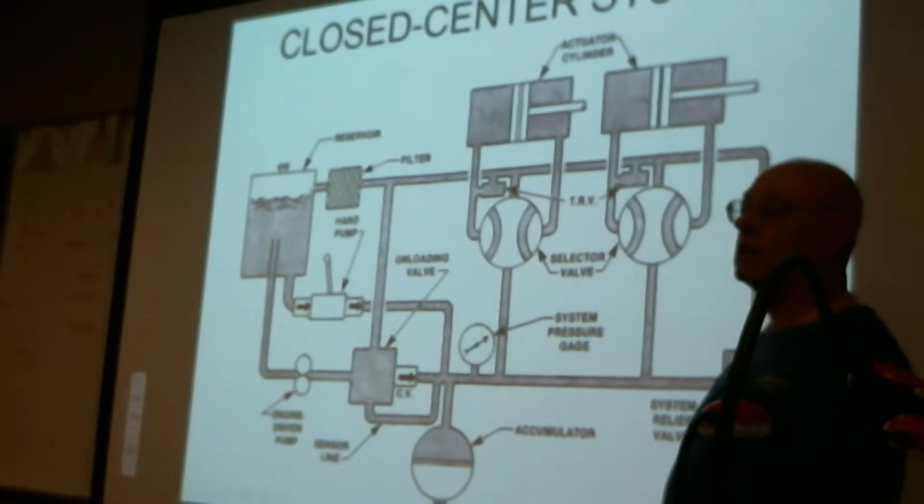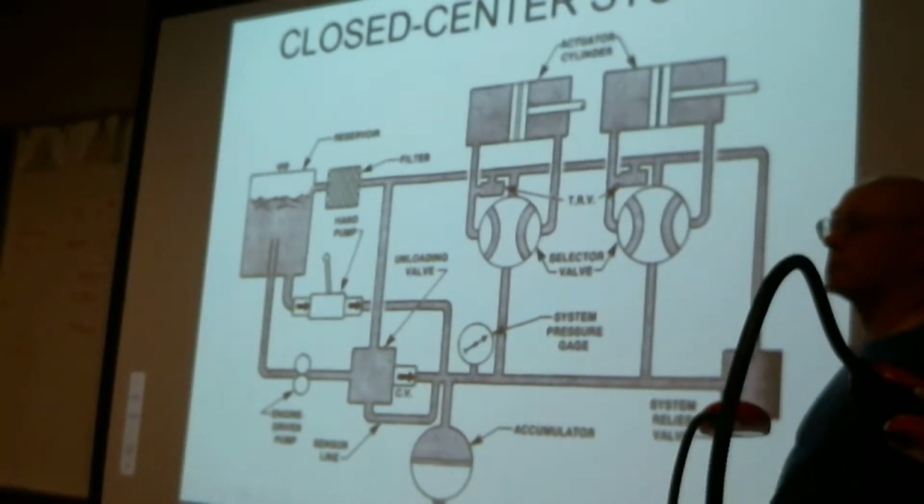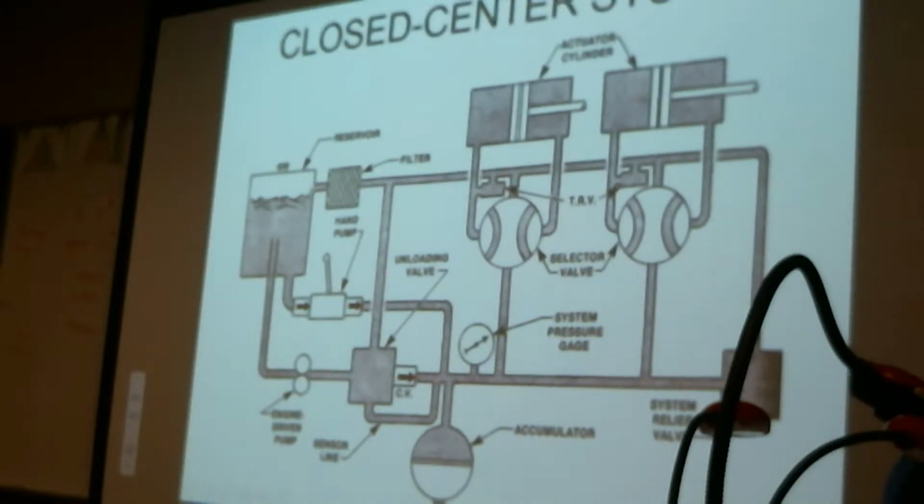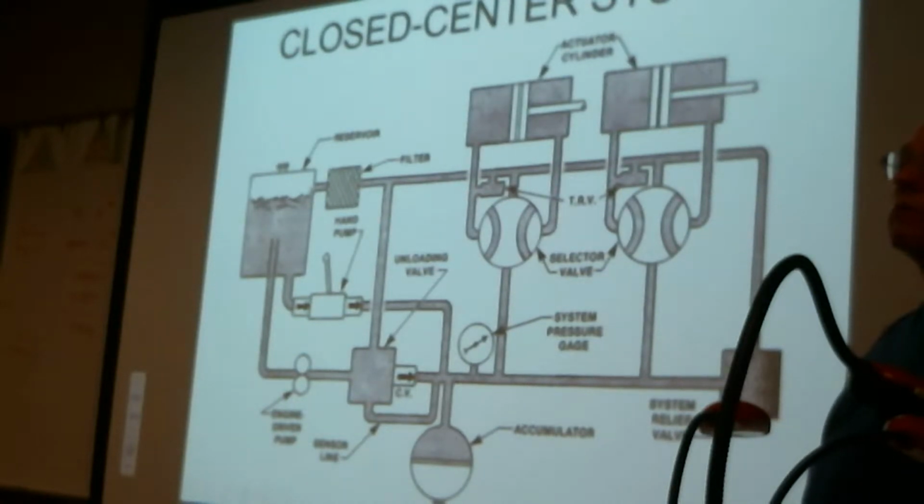If a heat buildup should occur, that heat buildup will cause the pressure inside of the cavities of that actuator to go out of control. So we have to find a method for controlling pressure. They are miniaturized versions of relief valves, but they've got a very strong spring in them. And if the pressure should rise inside of the cavity, the thermal relief valves will provide for a brief instant opening.